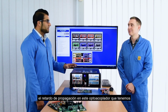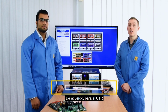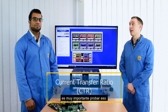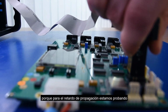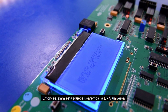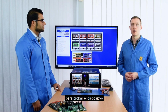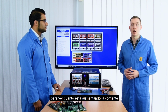So Oliver, in the previous episode, you showed us how we can test for the propagation delay on this optocoupler that we have. How about the CTR? Okay, so for the CTR, the current transfer ratio test, another parametric test, it's very important to test that because for the propagation delay, we're testing the speed, and for the CTR, we're testing the intensity, as our friends in South America would say. So for this test, we'll be using the universal I/O and auxiliary power supply to test the device to see how much the device is boosting the current on the other end.